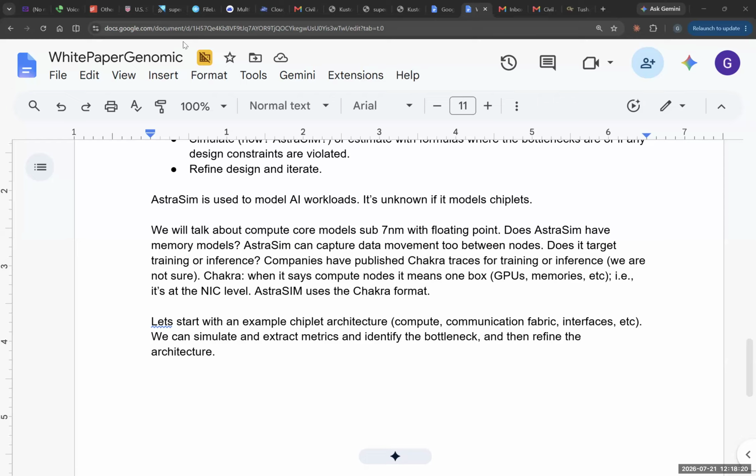How do you abstract the workload that's actually done on the chiplets? Because at least to my understanding, that is a very critical part. You have some set of chiplets because you've optimized them to do a particular task. You have a compiler that goes with that. That compiler then has to do the complex task of partitioning that workload amongst the chiplets, and that would determine where your bottlenecks are. You could take a very simplistic approach and say, well, I have a workload, I know that I have a compute phase, I know that compute phase has a certain TOPS, so therefore it will finish in X number of cycles on this chiplet. But I don't know if that is the level at which we want to abstract this, or is there a deeper level?